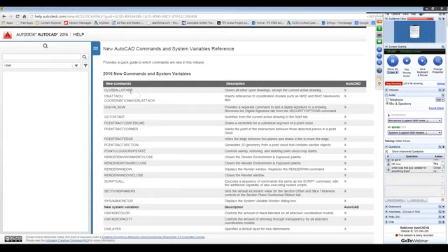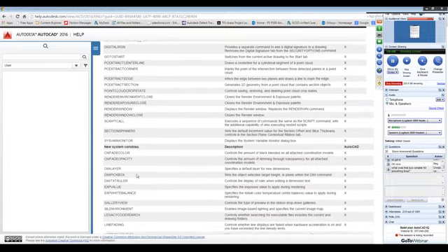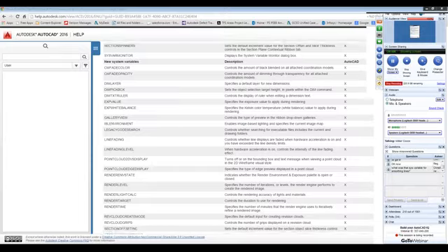And like close all other, we also have a digital signature which we can apply to our AutoLISP routines. We have a new method of scripting, and that applies to both AutoCAD and AutoCAD LT, which is called a script call, which actually allows you to nest your scripts within other scripts. Again, the dim layer we discussed last week. Here's some new system variables for the line fading, which was introduced last release. We can now actually change the intensity of fading, line fading, rev cloud grips.